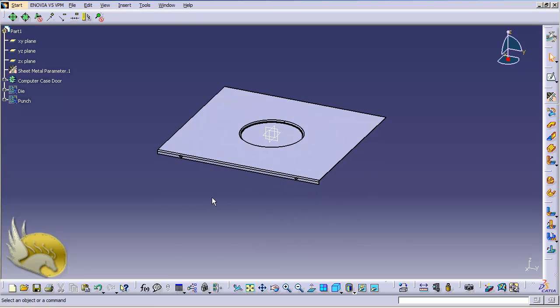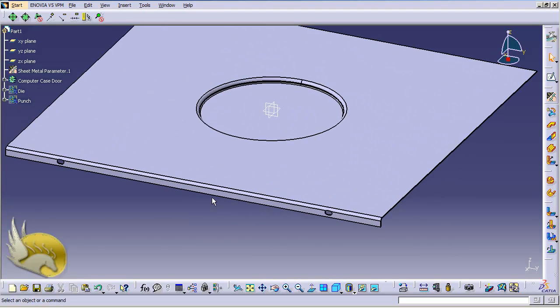And I want to change these elongated holes into circles. You remember that I selected these for the screws. But here, because I want to have an axis, and you know that elongated holes do not have an axis, I need to create a different type of opening here, and that's going to be a circular opening.